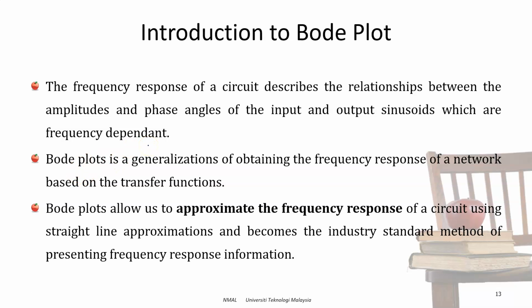In other words, it describes the relationship between the input and output in terms of amplitudes and phase angles. And the Bode plot is a generalization of obtaining the frequency response of a network based on the transfer function.